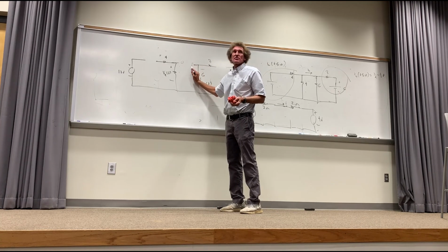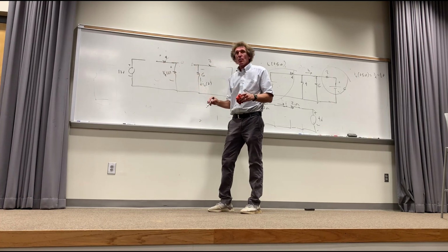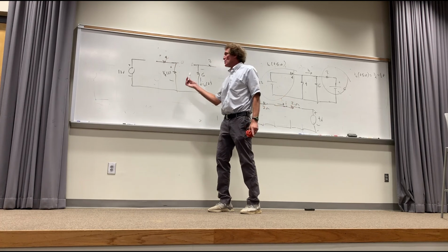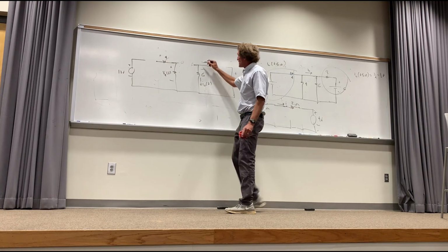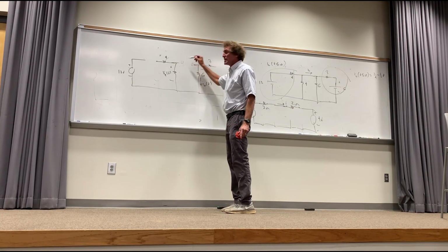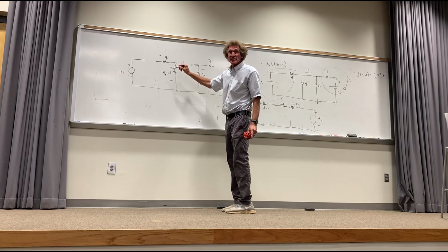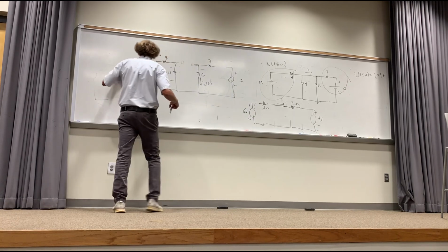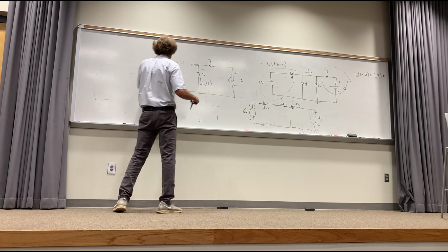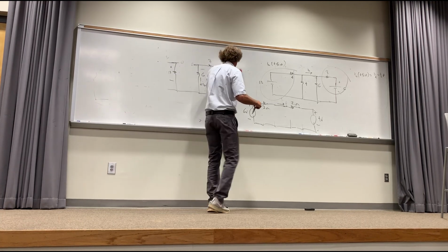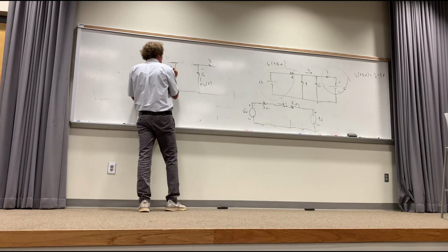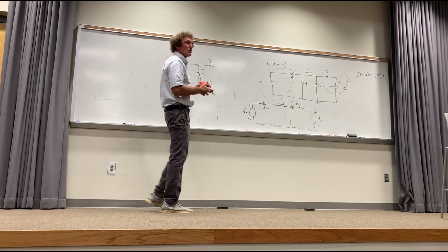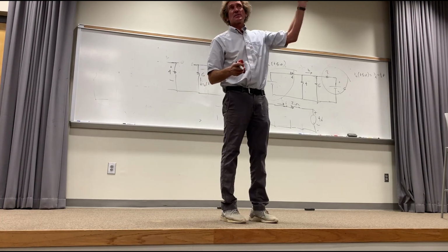Now, what's the Thevenin equivalent resistance? Do we care about that resistor, class? No. Why not? Because it's a short. No current can flow there. Do we care about this resistance? We care about only these two, and they are in series, right? This is effectively gone. Look. This is gone. That's gone. That's gone. Only the 6 and 4. What was that, a 3 or 4? 4? So it's 10 ohms. Agree? How many see this?